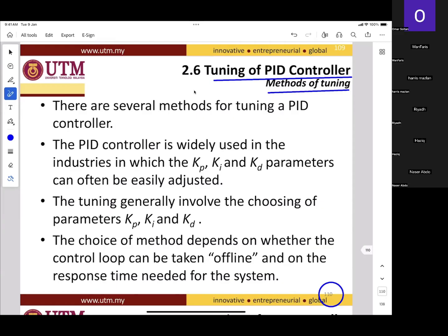But we do the calculations: find the zeta, find the dominant poles, find the new real part, find the new omega n, find the new imaginary part, and then we draw the new dominant poles, and then we estimate the value of zeros that fulfill our desired overshoot percentage, settling time, or new peak time.